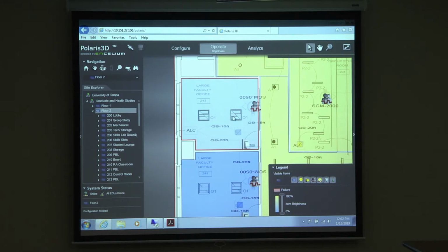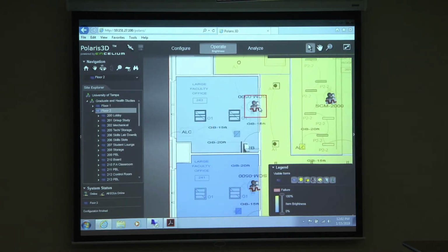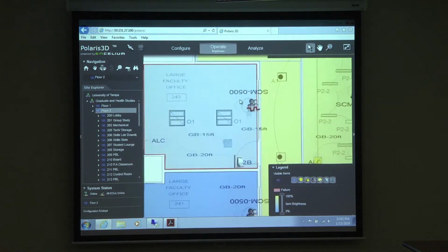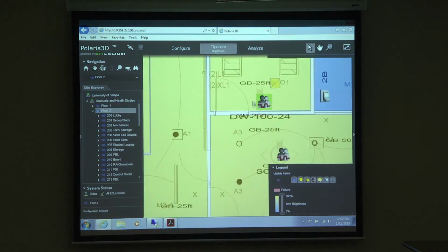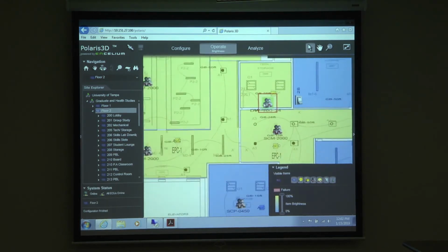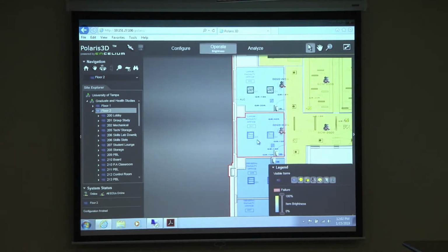And this is how I know there's nobody in there. So look at the occupancy sensor right here. See, the guy here is grayed out, right? If I zoom out, look at this sensor. This one here, see that little green around the occupancy sensor? That means it's seen motion, right? And that's why the room is on. So these ones that are grayed out, if you notice, the room is blue, I mean the room is off, right? So that's why I know there's nobody in there, right?